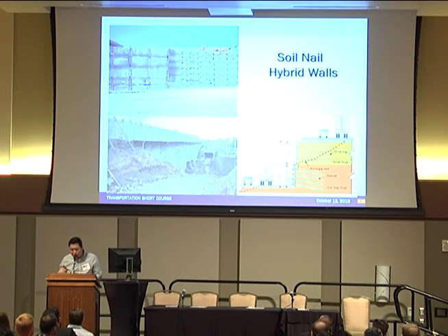So there are a couple of viable options. Once you finish the soil nail retaining wall at the bottom, you can build the fill wall as a temporary earth wall. Our bridge standard calls out the TW, RW using the metal grid system, but in this case you can build the TW, RW using geogrid. Then you can install the soil nail through the geogrid temporary earthwork.